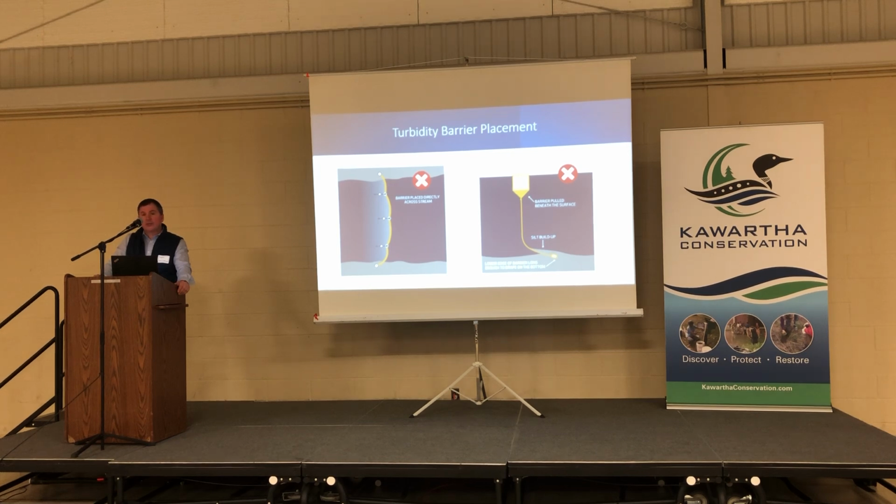And I do have to say, we see this often specified in applications where we need something a lot more robust, a lot more heavier duty to do the function. It has a woven geotextile body, as Matt is holding up here, different standard depths that are available, and then it's connected together in series using snap hooks and quick links to create the continuous connection.